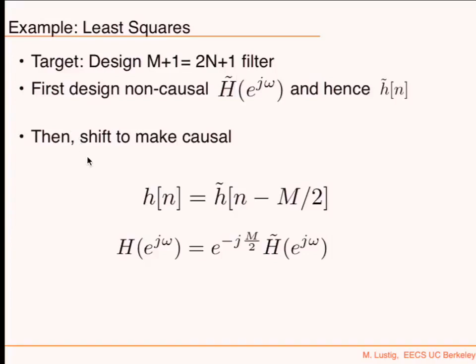And then after we design it, we're just going to shift it to make it causal, or apply a linear phase in the frequency domain, which is exactly the same. So after we design it, we're going to basically shift it by m over 2 to make it causal.